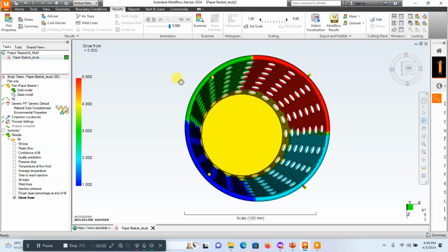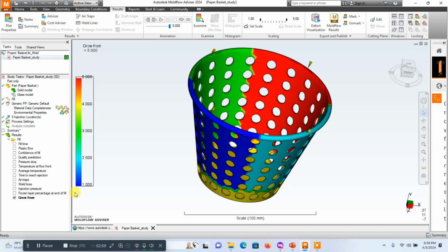The gate location analysis results can actually determine more appropriate gate locations in your part model, and the growth form result can also be improved in a number of ways. Now, furthermore, alterations usually have side effects, so after making changes it's very important for you to cross-check to see whether there are other problems that have been introduced due to your alterations.